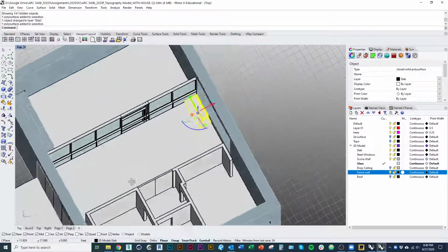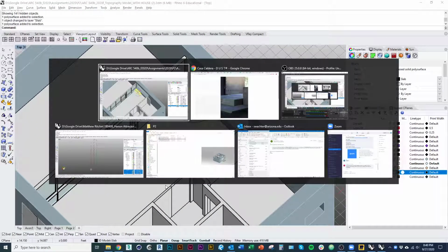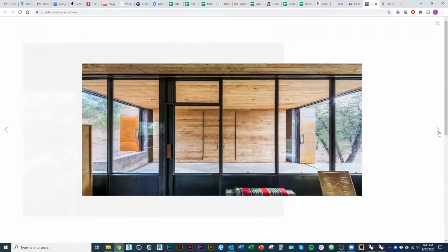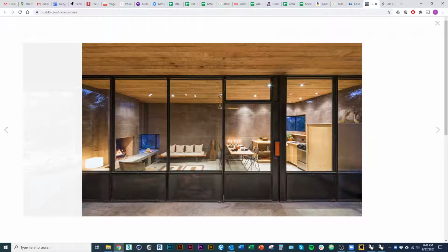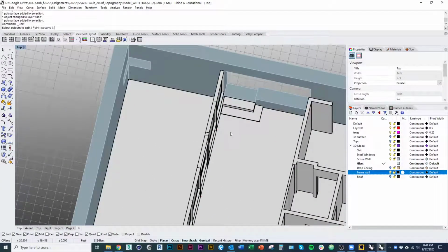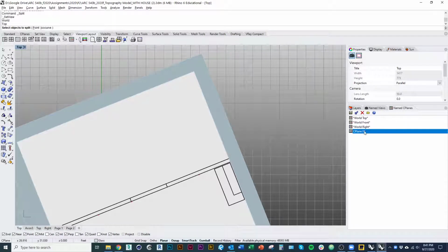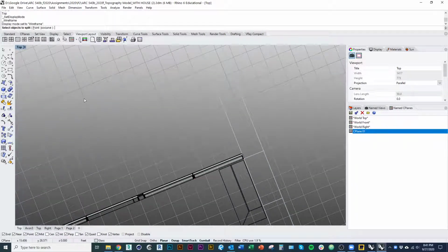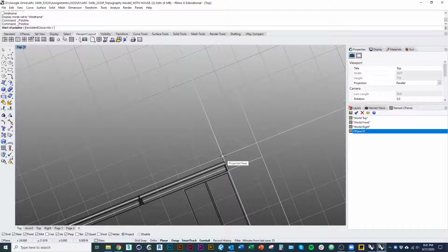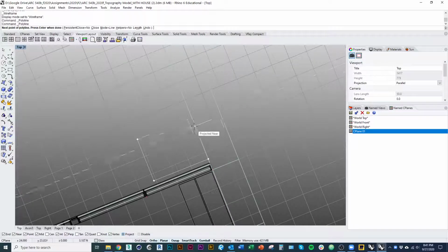The other thing that I wanted to show in this video is just a couple tricks with casework. So we're going to model some of the stuff with our kitchen countertops there. I should still have my plan with me, but I don't. Gotta make it up once again. And I'm using the command Polyline. I'm setting it to project so I don't draw crazy shapes in 3D that I don't want.